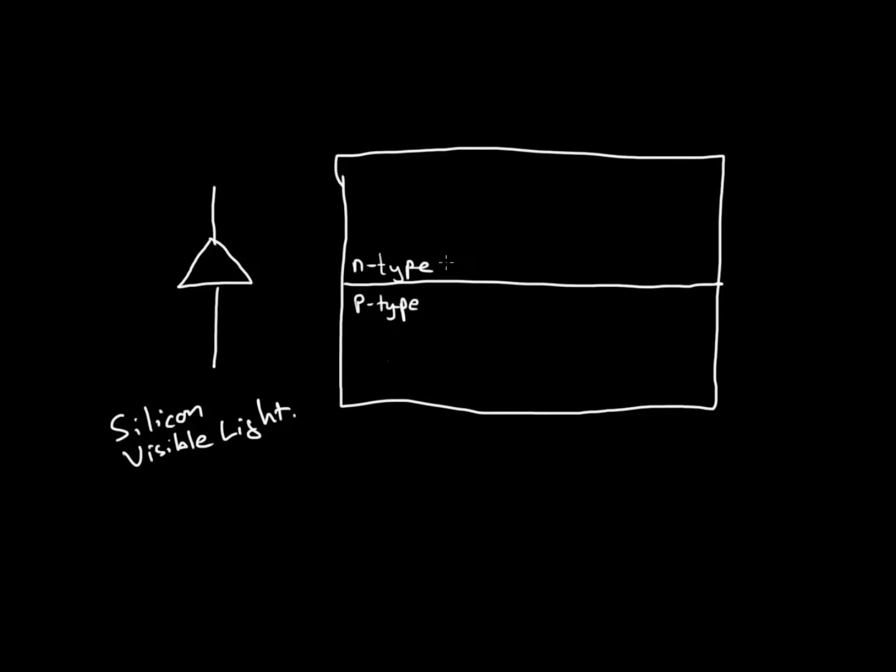So here in this discussion I have n-type silicon on the top and p-type silicon on the bottom. What happens? Well, when you put these two types of material together, you're going to have some depletion width. There's going to be some depletion region that grows around this junction, and it's going to start here, say, and the width, this direction, will depend on the doping profile.